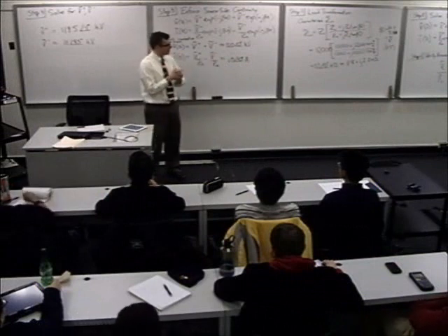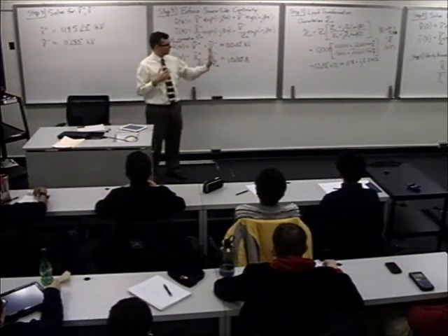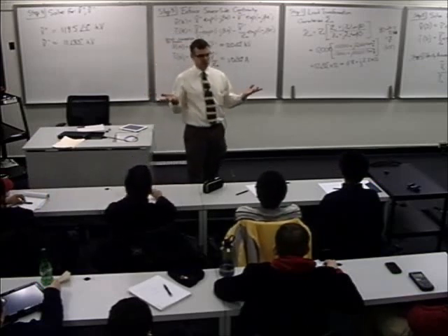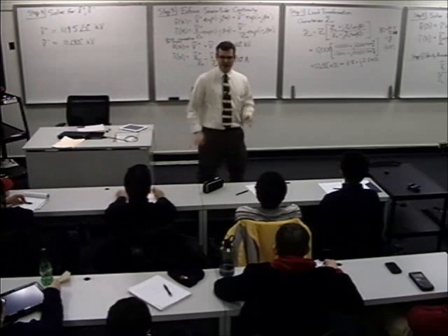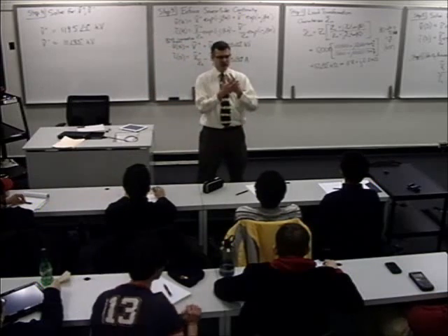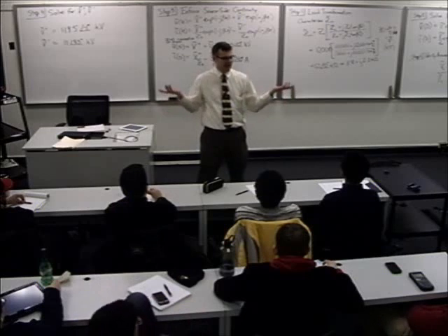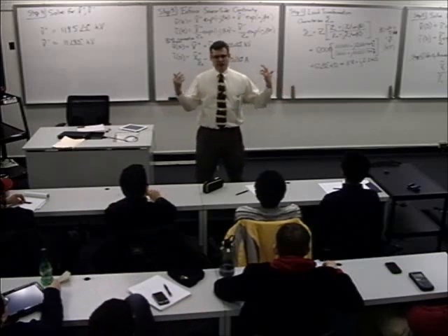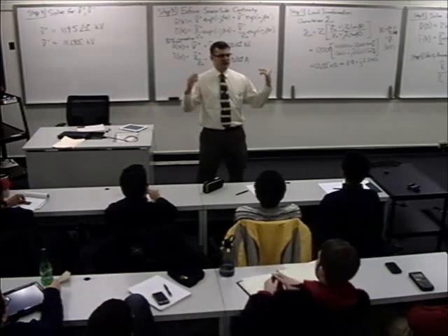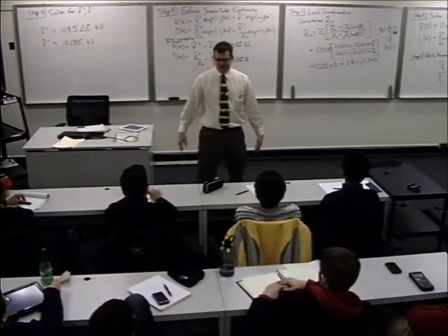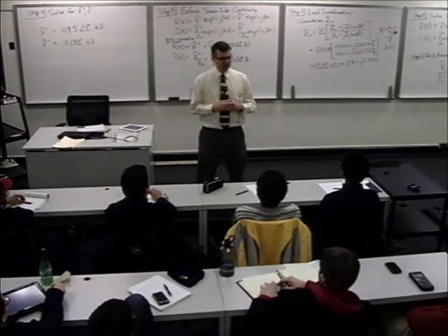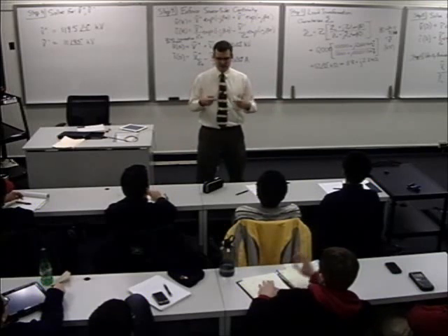I'll also note that we worked through a solution here, and when we're done with the solution, we've got everything we need to characterize this network. We know what the input voltage is, the input current, the output voltage, the output current. We know the forward and backward propagating waves. So at this point, I could ask anything you wanted to know. What is the total voltage on the line 7/32 of the wavelength down this line, or something like that? You can characterize everything at this point. It took a lot of work to get there, but you see there's a lot of rich behavior going on.